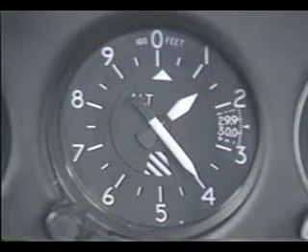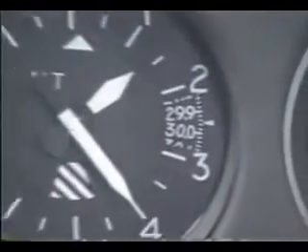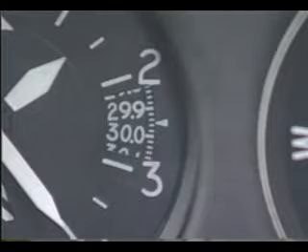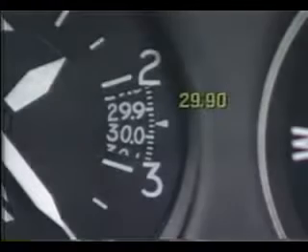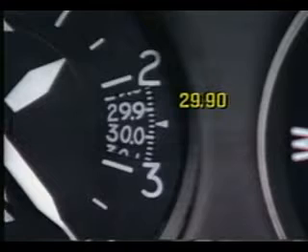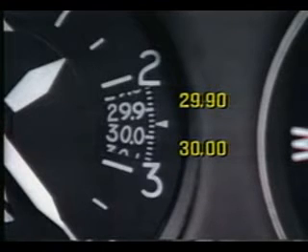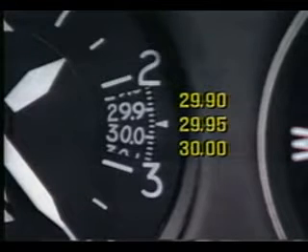The altimeter also has a barometric scale which can be adjusted to compensate for variations in atmospheric pressure. Here you can see the numbers 29.9 and 30.0. You read these by adding a 0 to each number to get 29.90 and 30.00 inches of mercury. The barometric setting on this altimeter is read as 29.95, since the pointer is halfway between 29.9 and 30.0.